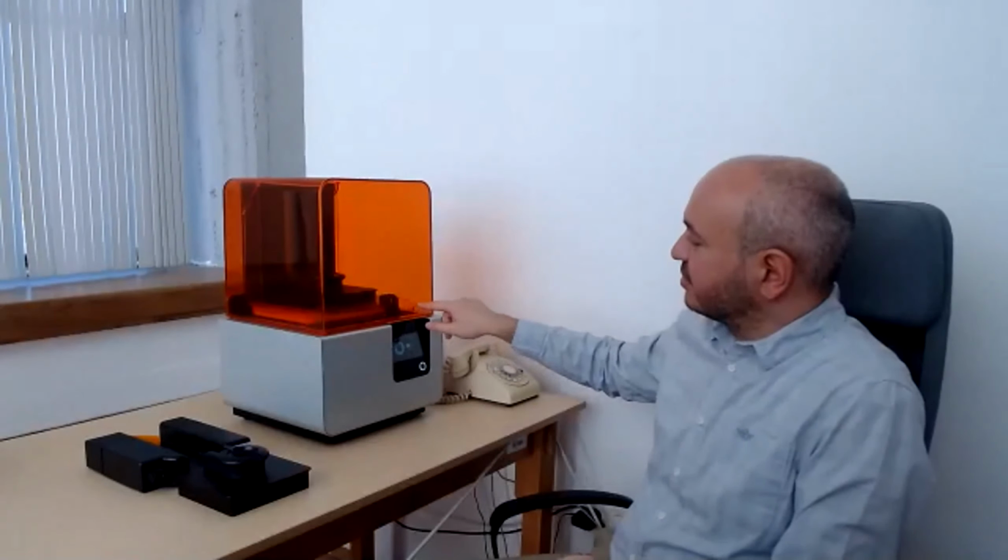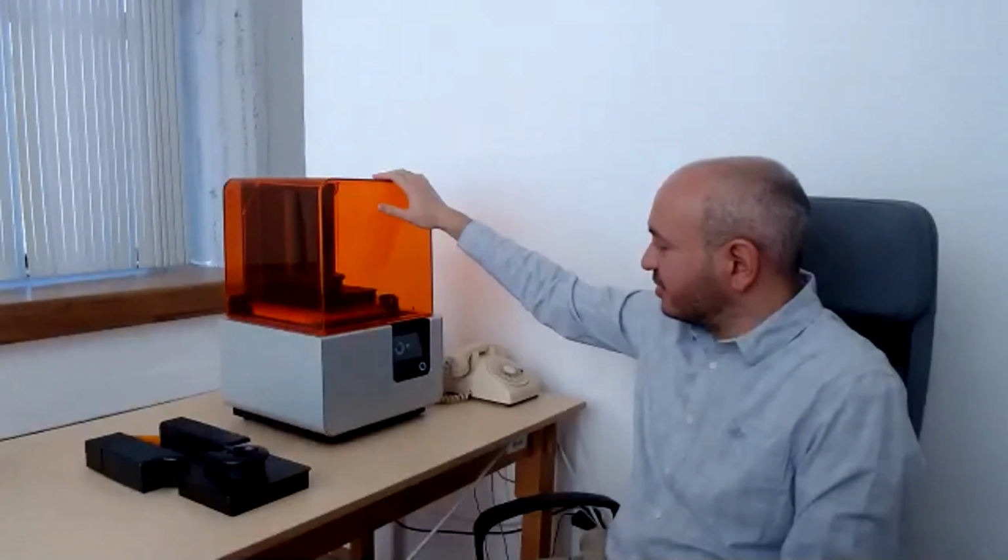So I think you see the printer here right now. This is a stereolithography process, and you make use of resins. Inside there's a tank here. I cannot open this door since, as you know, the materials are light sensitive. If you open it, then some portion of the material will be solidified and your resulting product will not be successful.